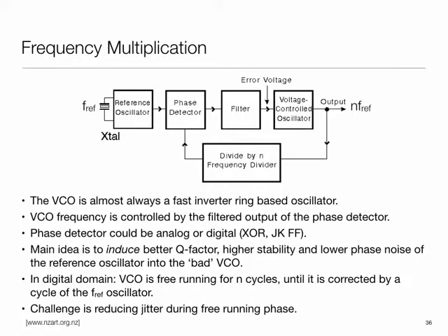So then we create a circuit which detects phase error between the two, smooth it out, and then feed it as a voltage signal to the voltage controlled oscillator. So essentially we create a little control loop, and the idea is that if the control action works as expected, then this would stabilize at n times f_ref, and the error would be driven down to 0.